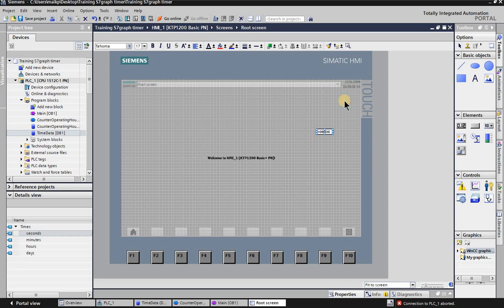And then you can actually go ahead and do the design of it, because right now how it looks, it's pretty generic. It shows you 5 digits plus or minus sign, positive, negative in front of that, and we actually want to get rid of that because with seconds, minutes, hours, we only have 2 digits, and we don't have negative hours or seconds, so we also want to get rid of that plus sign.